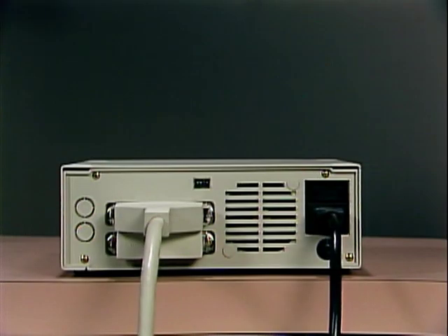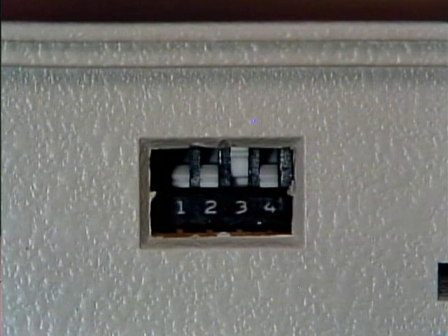The back of the RRD40 drive has a panel with two I/O connectors. The I/O cable is attached to the top connector on the drive. Because the VAXstation 3520-3540 workstation supports only one RRD40 drive, a terminator must always be installed in the bottom connector. The RRD40 drive is an FRU. The dip switch pack located at the rear of the unit determines the drive unit number. Check the VAXstation 3520-3540 maintenance guide to find the switch settings.